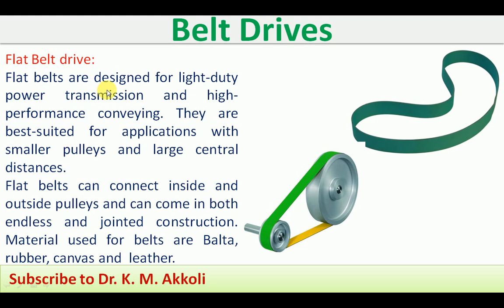Flat belts are designed for light duty power transmission and high performance conveying. This belt is flat. We can see here the belt wrapped over the pulley has a flat surface, and that is used for light duty and higher power performance conveying. They are best suited for applications with smaller pulleys and large center distance.